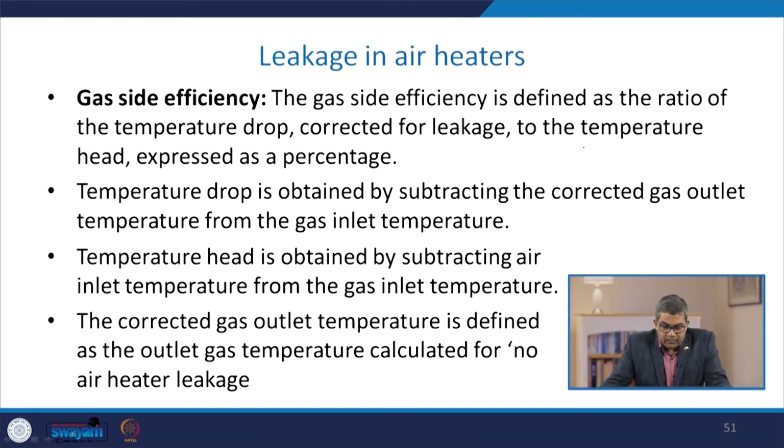Now, when we talk about the leakage in the air heaters, we cannot overlook the importance of gas side efficiency. The gas side efficiency is usually defined as the ratio of the temperature drop corrected for leakage to the temperature head, expressed as percentage.